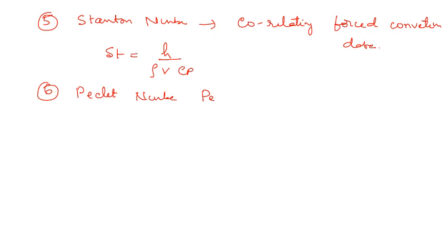The seventh number we can give is the Graetz number. It is related only to the heat flow to the fluid flowing through a circular pipe. It is defined as the ratio of the heat capacity of fluid through the pipe per unit length of the pipe to the conductivity of the pipe.